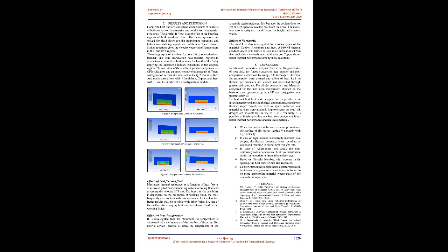Grid independency. The model is tested for grid independence to give proper resolution to the region where large gradients of fluid flow and heat transfer characteristics are predicted. The fine grid mesh for the x and y directions is adopted to properly resolve the velocity and viscous shear layers and to more accurately define the conjugate heat transfer at the surface of the channel, thereby improving the temperature resolution. For the meshing along the axial direction, away from the entrance region, a relatively coarse grid system has been taken.